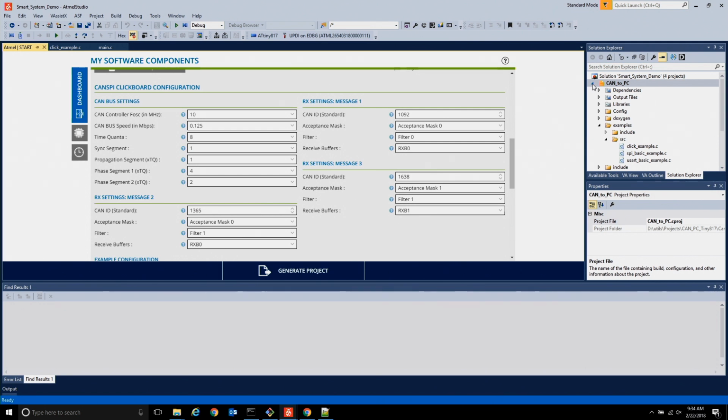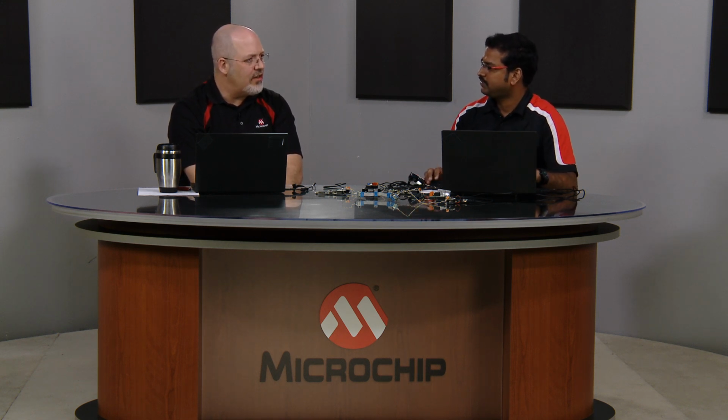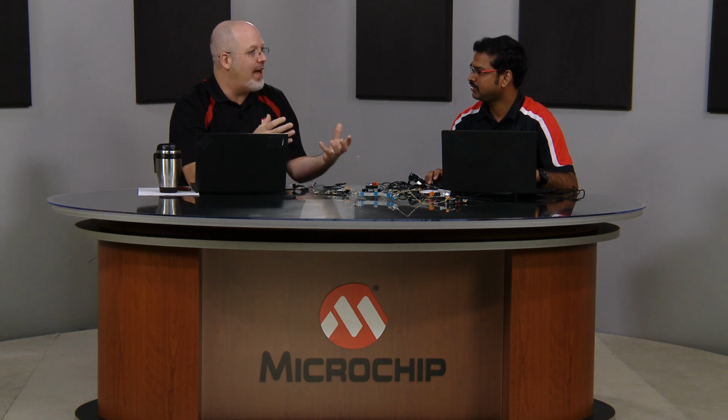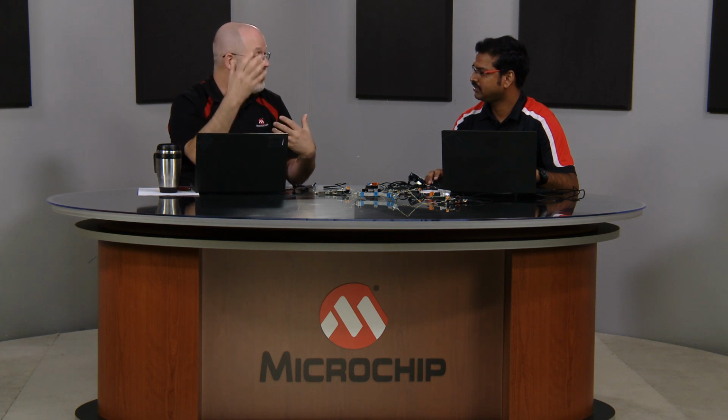Now if you wanted to make some changes at runtime on your application, as I understand it, Start creates some functions that you can use in the background. Can you talk about those? Say I'm running a PWM, and for whatever reason I want to change the duty cycle. How do I do that? While the microcontroller is running the application, I can't go back to Start, so I would need to call a function. Can you show us any of those?